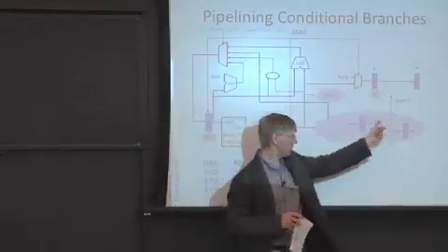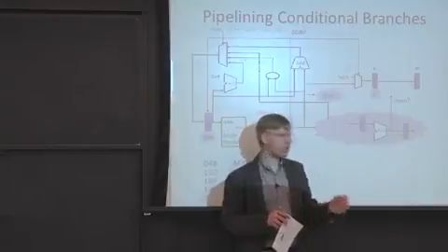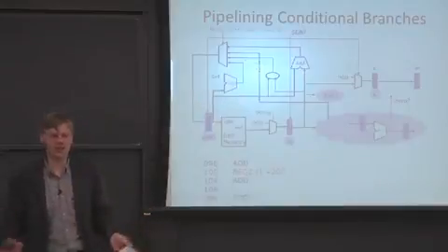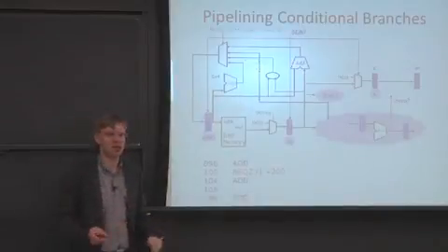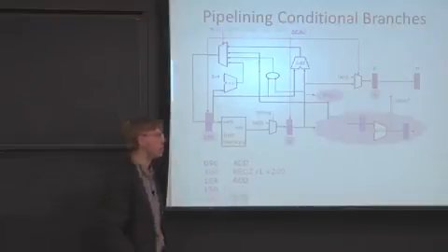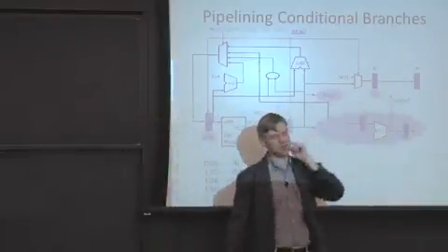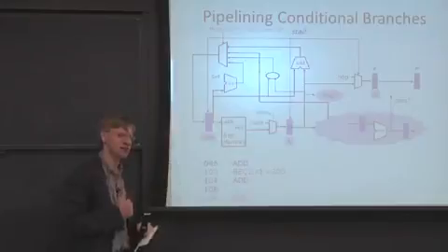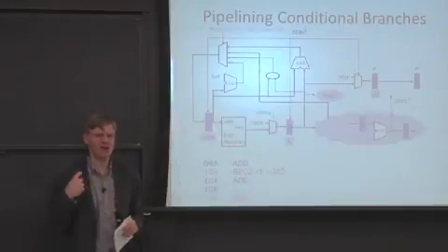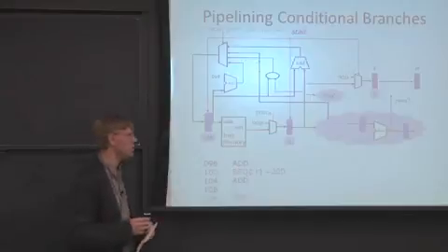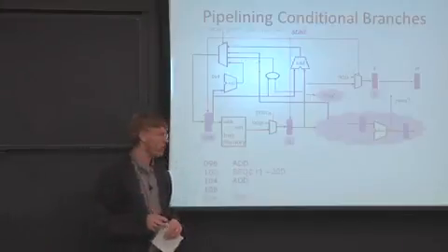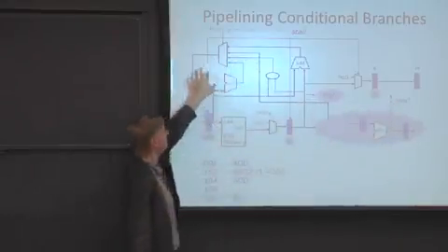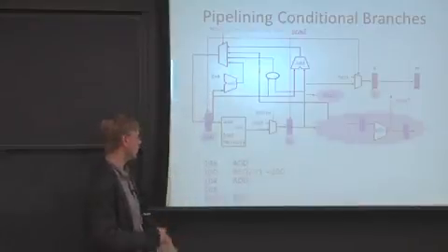Unfortunately, we need to do a comparison here. And the hardware we want to use to do the comparison is in the ALU. It's a subtract operation or a comparison operation. So this fits well within our arithmetic logic unit. And we have the 0 wire coming out. So instead of having one cycle of latency or one cycle of kills being inserted, we might have to insert 2 cycles. Because now we have to wait for the branch to get to here. And if we are predicting PC plus 4, we're speculating PC plus 4, we will actually have fetched more data.